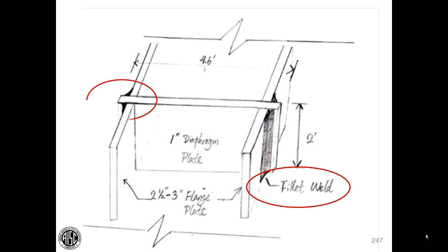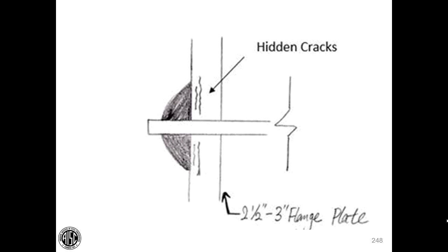The geometry suggests the 1-inch plate is the same as the outside plates, even though it does say that they're 2.5 to 3 inches, but graphically you don't get that kind of image. And look at this. It shows lamellar tears, but the lamellar tears are shown in the 2.5-inch thick material, not in the 1-inch material. You see, this repeating of history is flawed, and we aren't going to learn the right lessons. Not if we don't accurately record history.